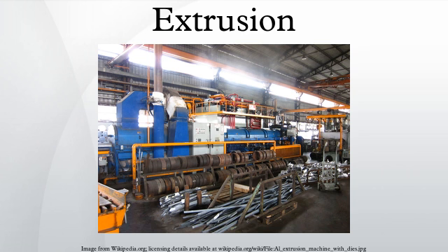Plastic. Plastics extrusion commonly uses plastic chips or pellets, which are usually dried in a hopper before going to the feed screw. The polymer resin is heated to molten state by a combination of heating elements and shear heating from the extrusion screw. The screw forces the resin through a die, forming the resin into the desired shape. The extrudate is cooled and solidified as it is pulled through the die or water tank.